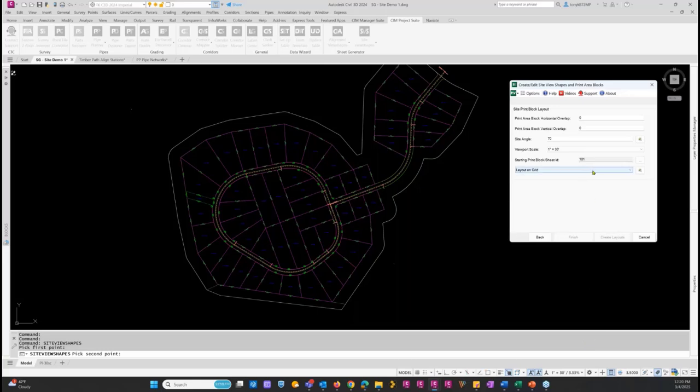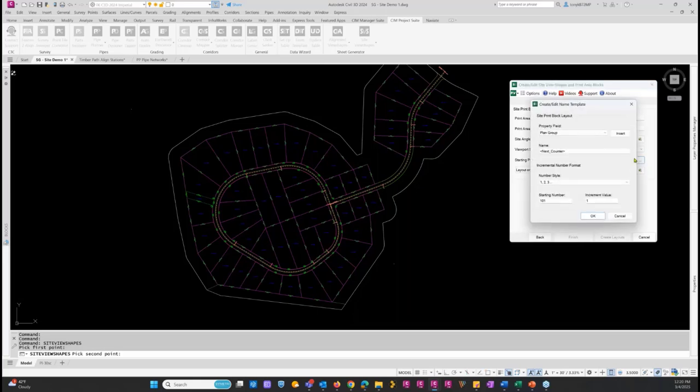automatically for you. Then we have our sheet numbering. How do we want those numbered, and that's pulling from our block that we include. If you're using your own, make sure that you have an attribute in here that this reads from. I'm giving the starter number, counting by 1. We can do some other things in here if we want to include things. I'm just going to go next counter. This is standard, pretty much AutoCAD stuff, if I wanted to put that in here. Leave it at next counter, increment by 1.